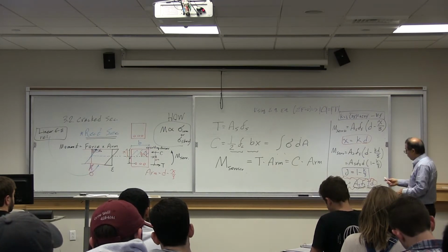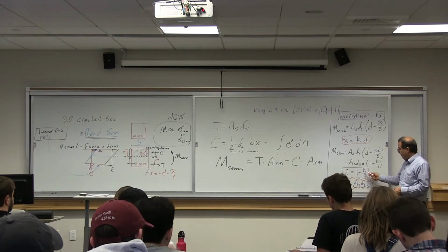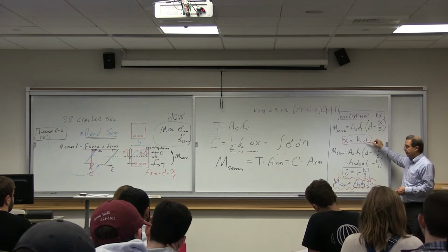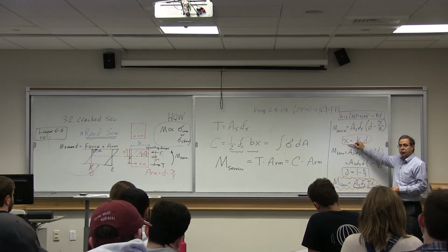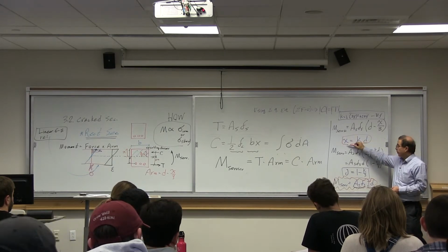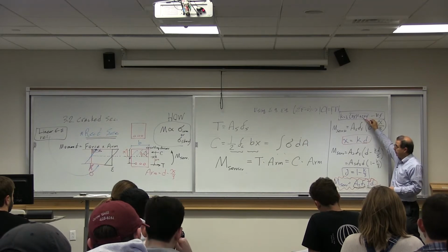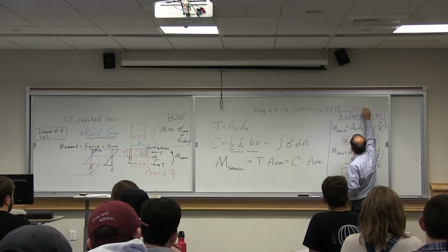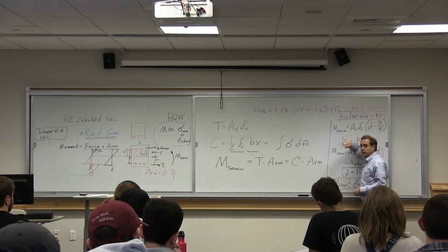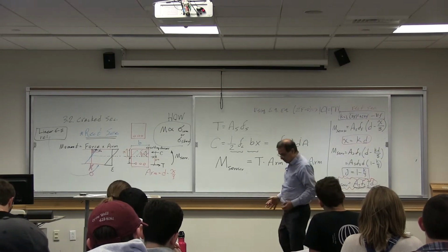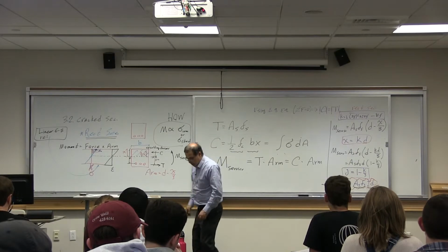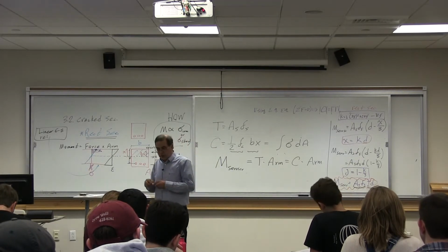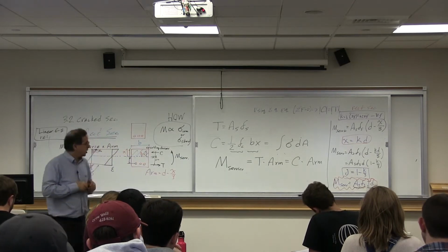J is simply 1 minus k divided by 3, where k is a constant multiplied by effective depth that gives you the compressive depth, which can easily be calculated based on this. All of these are for rectangular sections only. If you have a different section, we need to do it differently. At this time, we are just talking about rectangular sections.